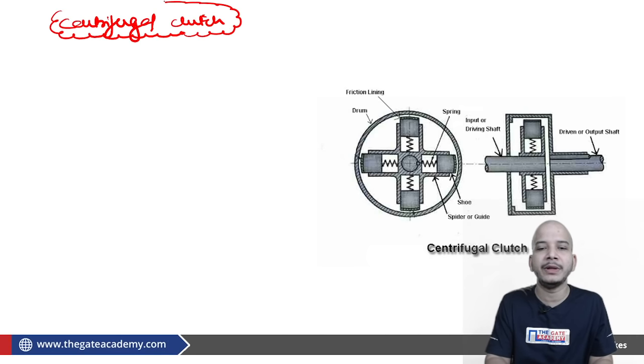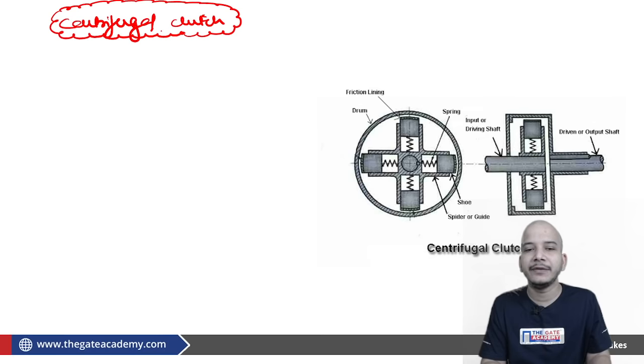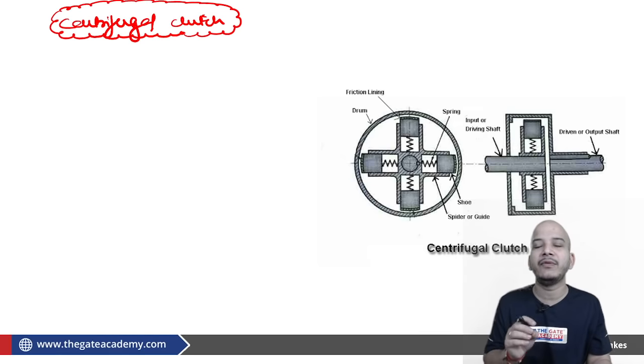For the centrifugal clutch, you should know the concept of centrifugal force. Centrifugal force is an inertial force, an imaginary force, after the application of which we can consider our body to be in equilibrium. However, in reality the body is not in equilibrium. The body is in a dynamic condition. The body must have some acceleration in a particular direction. But as far as centrifugal force is concerned, it is an inertial force. The concept of D'Alembert is to bring a body which is actually in a dynamic condition into a static condition and analyze it accordingly, so that we can have the ease of static equations.